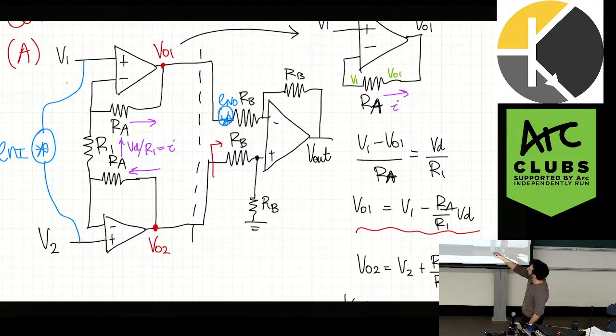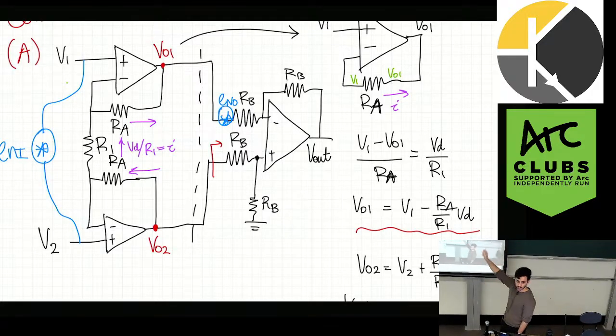Now, it doesn't actually matter which pin this is on. It can be on either pin. You can prove that to yourself mathematically, but it doesn't matter. Why is the noise shown on both the pins? Because that's how it's given to us, unfortunately. What they're saying on the data sheet is that the noise from the first stage is that, and the noise from the second stage is that. So they've given it to us separately rather than as a combined quantity.